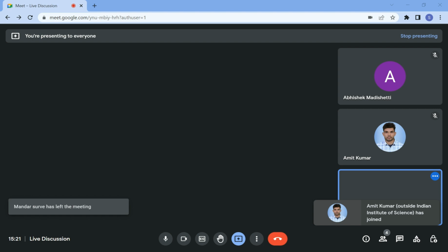Then from the same condition, we also got the second locus, which was in the vertical plane, which was a circle, and to locate the point B in vertical plane, we had another information that the front view makes angle 55. So any line that intersects this circle at 55 will be the point B. So now this is our final projection of the line.